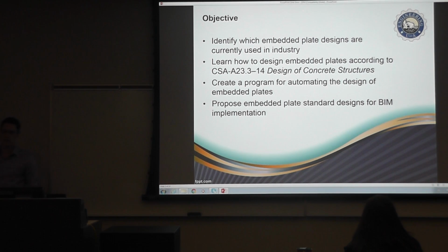The next part was to learn how to design embedded plates according to CSA A23.3-14 Design of Concrete Standards. This was necessary so that we could design standards that were in accordance to Canadian concrete standards. Next would be to create a program that would use these standards to automatically create embedded plates and test them and see if they work in certain conditions or not. And finally, propose embedded plate standard designs for BIM implementation.